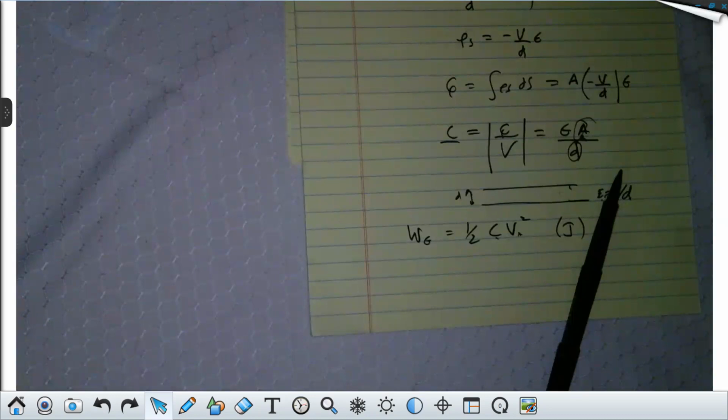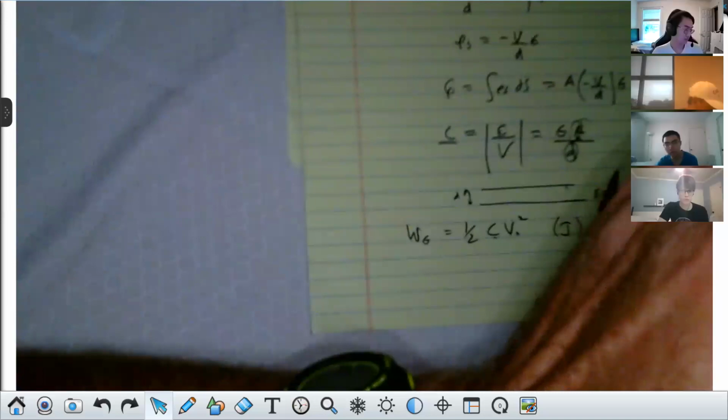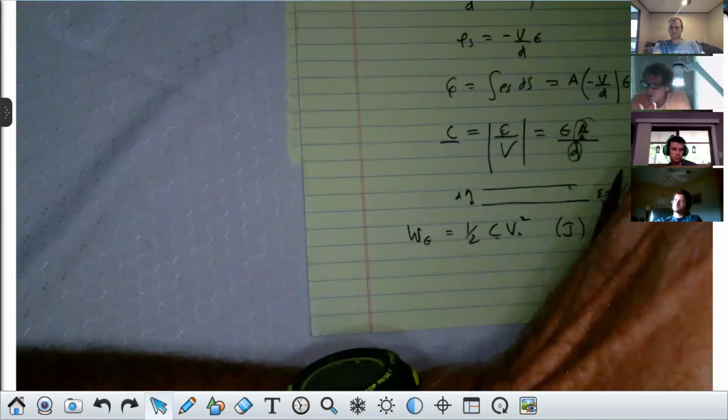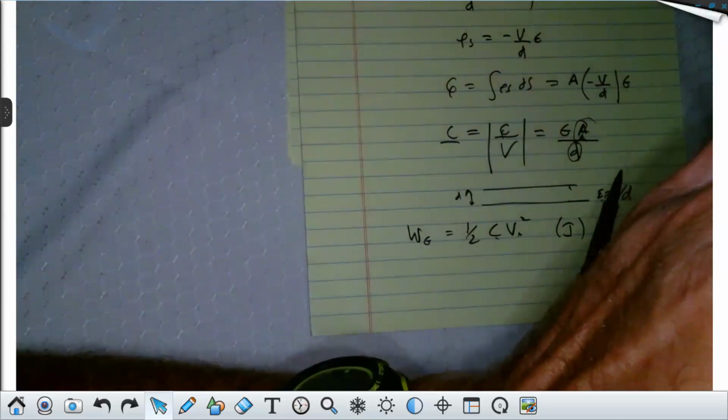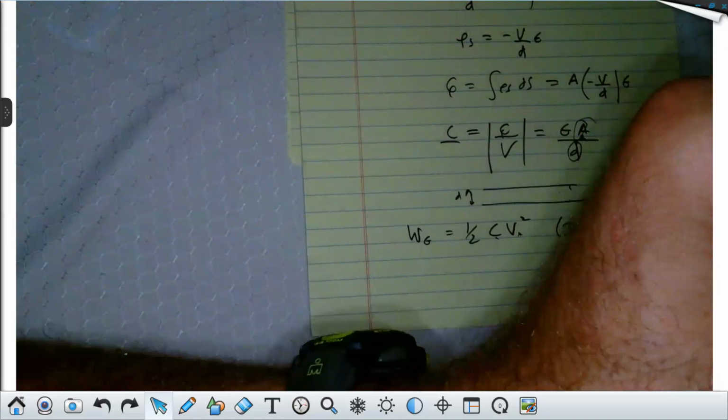They're called an electrolytic capacitor. Have you heard of this? Anybody? Electrolytic capacitors allow a huge amount of energy to be stored, and they have a fair amount of breakdown strength, but they can only be polarized one way. So if you have the plus to minus, you can only put plus minus voltage. If you invert that, they'll blow up.